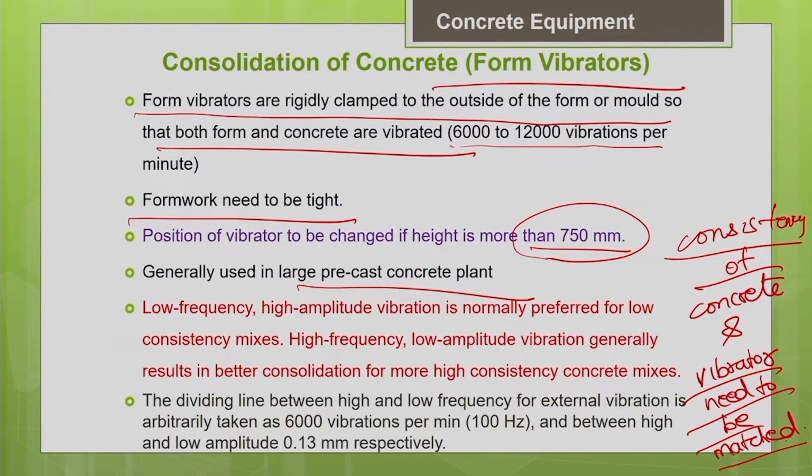Another important thing is the frequency and the amplitude of the vibration needed. That also depends upon the consistency of your concrete, because that is going to govern the efficiency of your vibration. Basically, for dry mixes which have low consistency, obviously the spacing between the particles will be more, because there will be a lot of voids in the dry mixes. In stiff mixes or low consistency mixes, there will be a lot of voids.